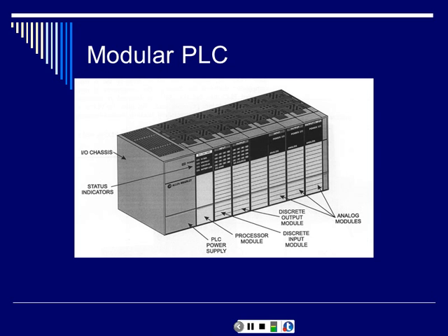The very first module, which is always numbered 0, is the processor module. And then your next two can be your input and your output, or you can space them out. You could have 2 inputs and then 2 outputs, whatever you have. But ours is input and then output.